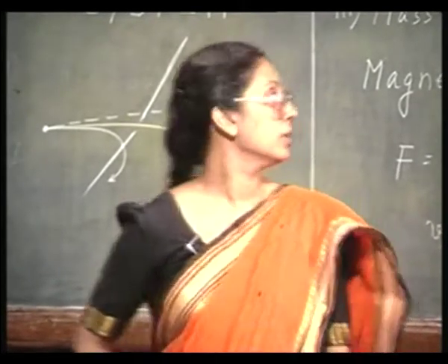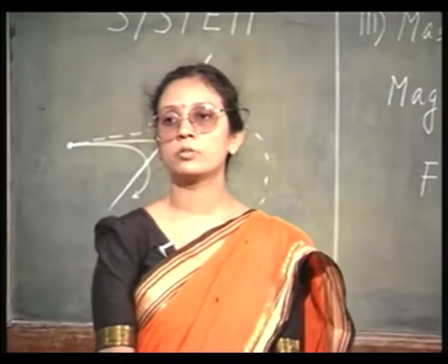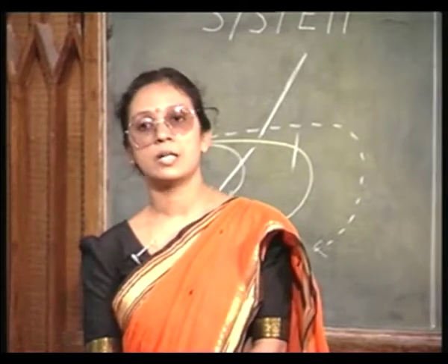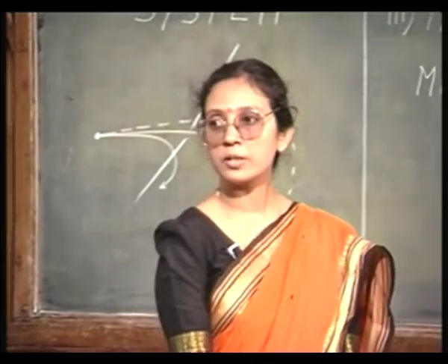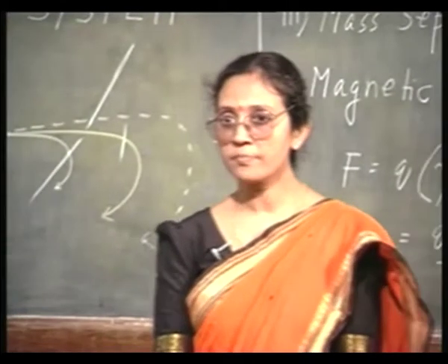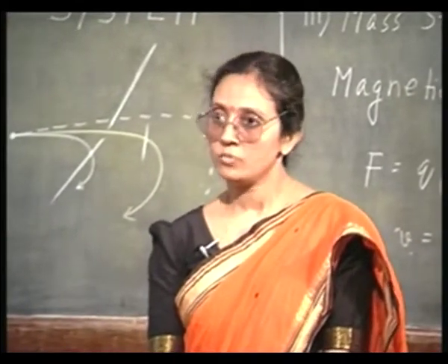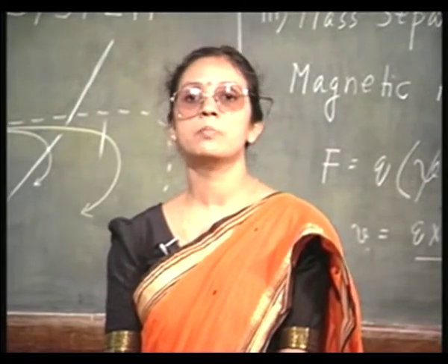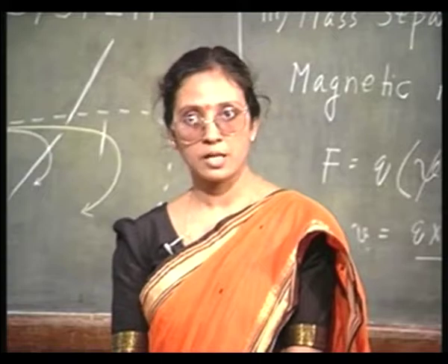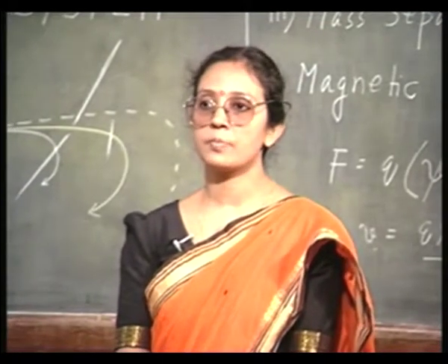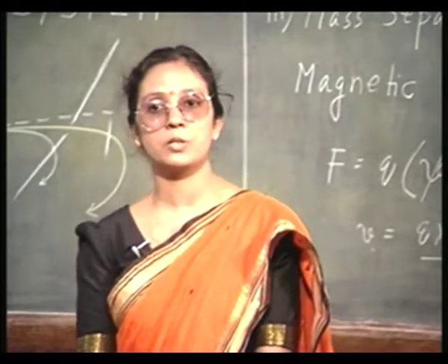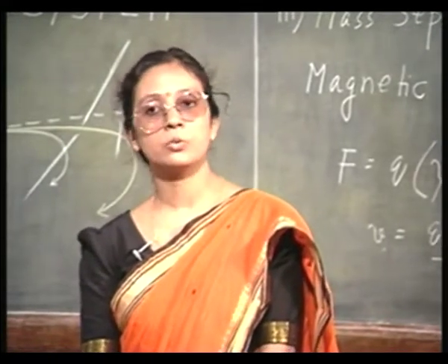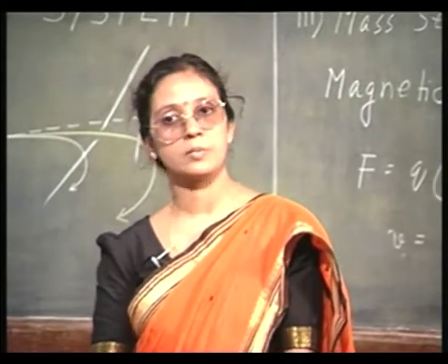So, these are the 4 important parts of the implantation system. First of all, the ionization, the ion source, the dopant material as well as the ionization scheme, where you are creating the dopant species, the ionized species. Then you have the accelerator, where you are imparting velocity to this ion beam. Then you have the mass separator, where you are selecting a particular ion species, and finally the XY scanning in order to implant selectively over the semiconductor material.